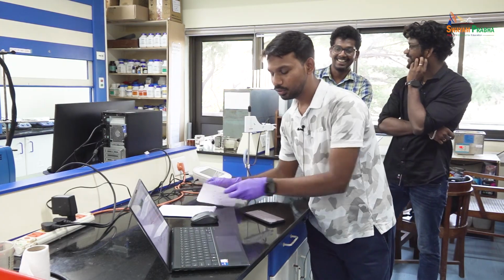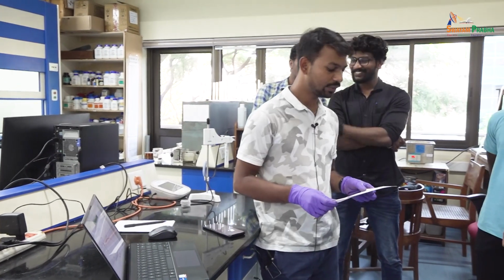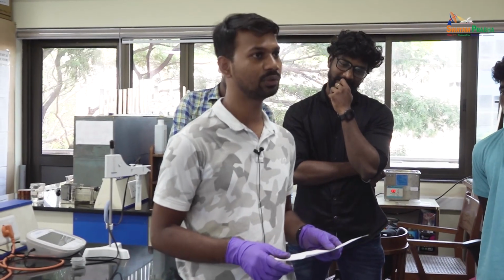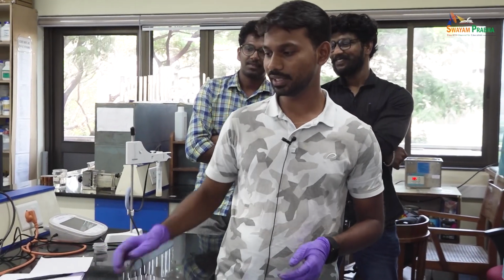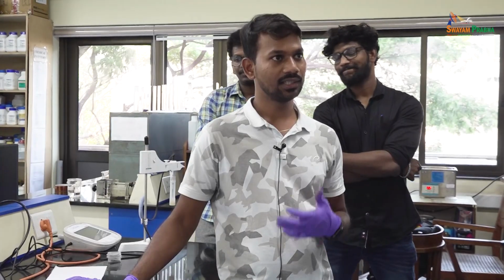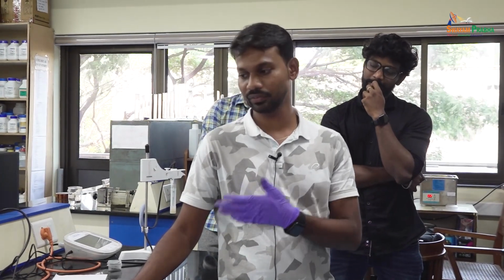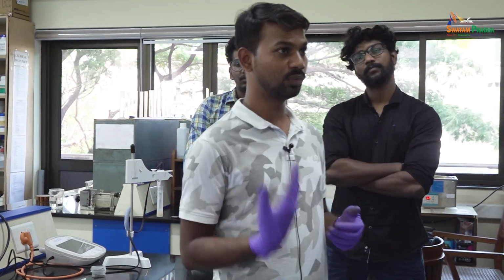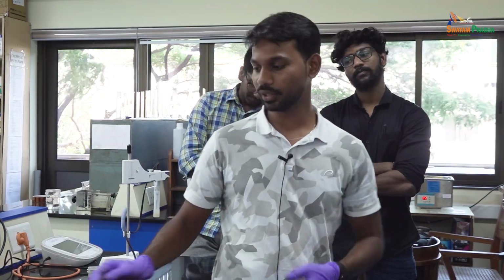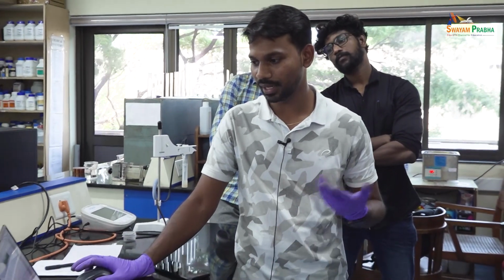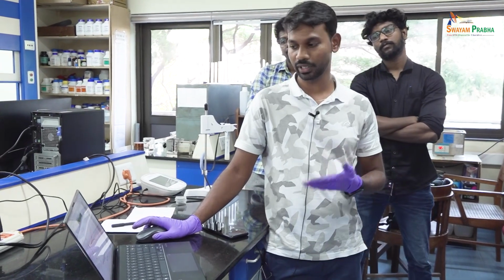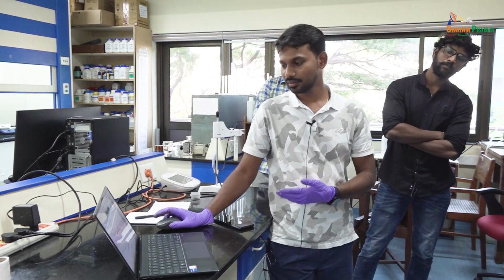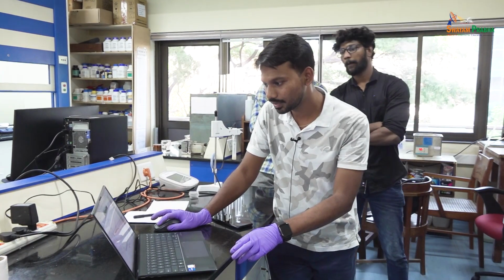So in the acid rain solution, the current density value is 1.17 microamp per centimeter square, whereas in the case of NaCl solution, it is 9.2 microampere per centimeter square. From this you can tell that in the acid rain solution the current density is lower, whereas in the NaCl solution it is more. You can attribute this to the higher chloride ion concentration. If you are working at a very low concentration or ambient in any other electrolyte, the chloride concentration won't be that much. So, depending on that, it is one of the factors that decide the corrosion value.